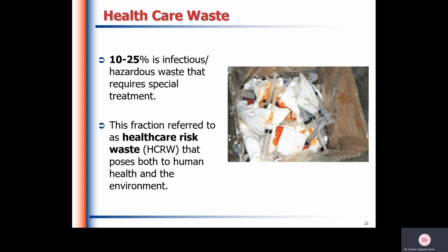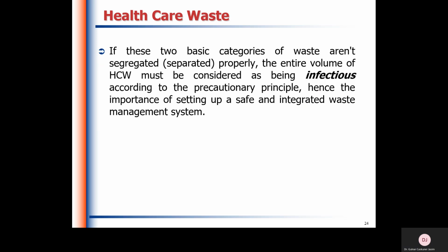10 to 25% of the healthcare waste is infectious and hazardous waste that requires special treatment. This fraction is referred to as healthcare risk waste, which poses both human health and environmental risks. If these two basic categories of waste are not segregated properly, the entire volume of healthcare waste must be considered as being infectious according to the precautionary principle, hence the importance of setting up a safe and integrated waste management system. They have to be segregated initially in a safe format.